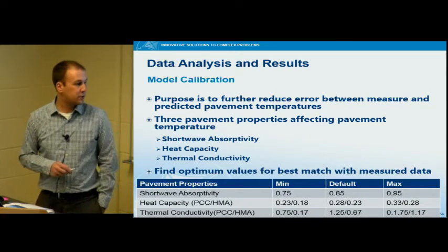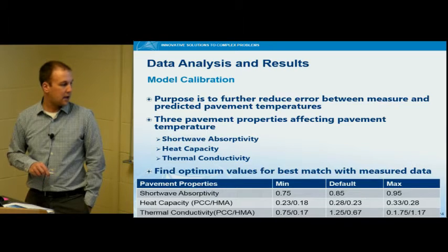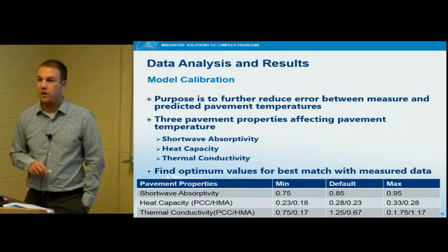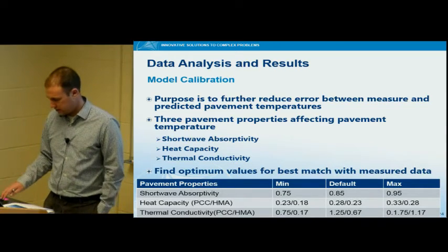So you can see the Pavement ME default values are right here. The PCC and HMA values are a little bit different, and the same with thermal conductivity. And we just moved it up and down by not much, just to see if there is a difference in predictions.